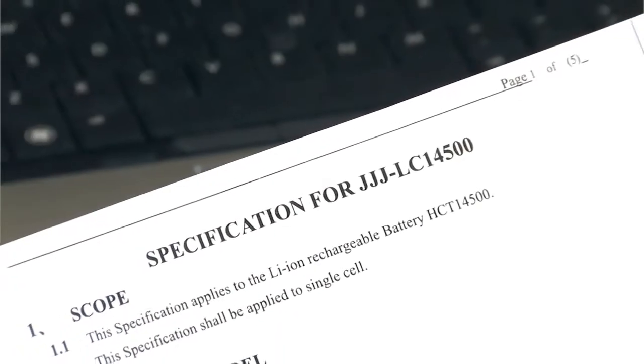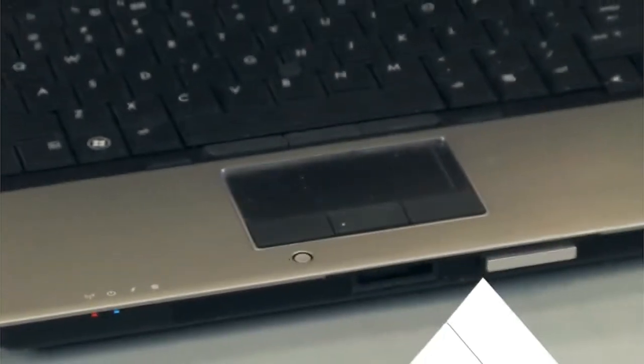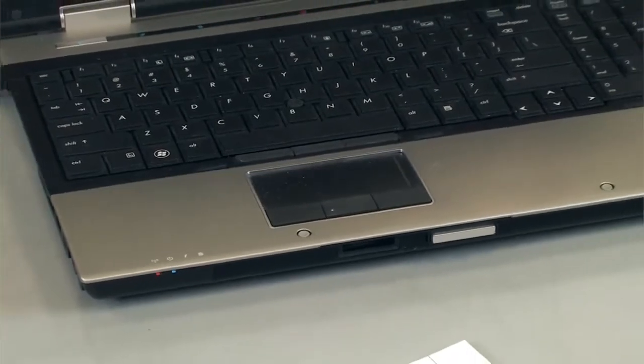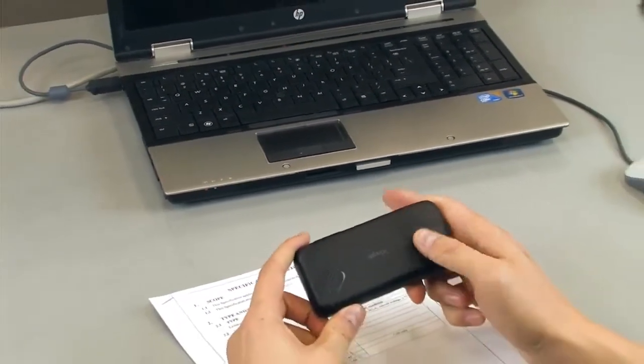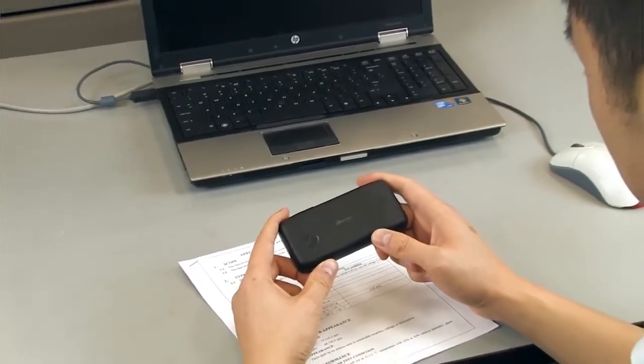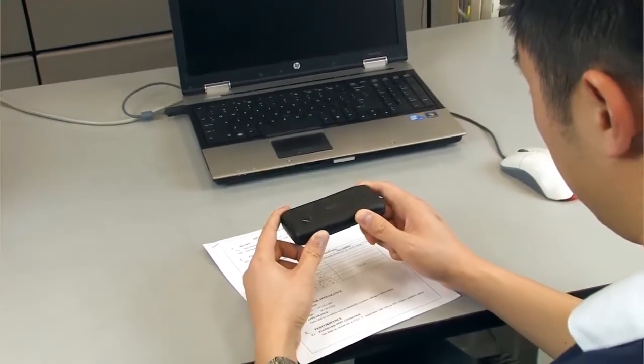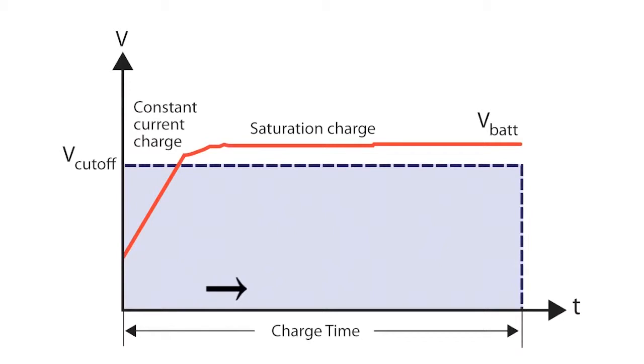You can also compare the battery capacity and energy obtained in actual use against the battery manufacturer's ratings to determine if there are any significant differences. It is important to verify the low battery shutdown threshold and also the full battery charge termination point for rechargeable batteries. This will tell you if the mobile device is making full use of the battery.